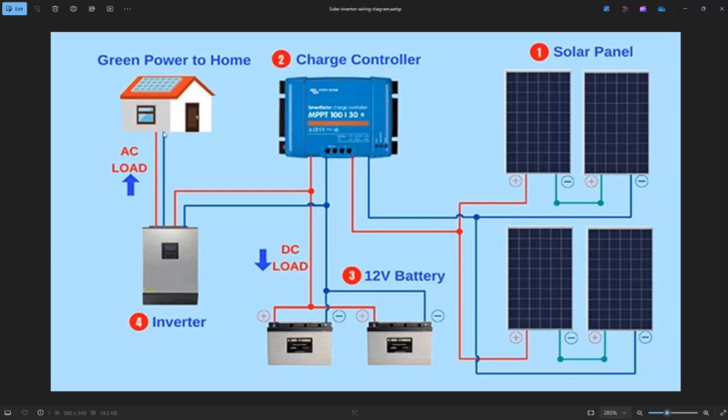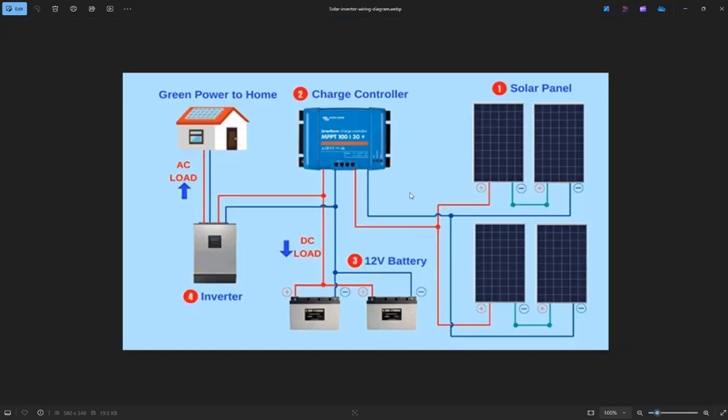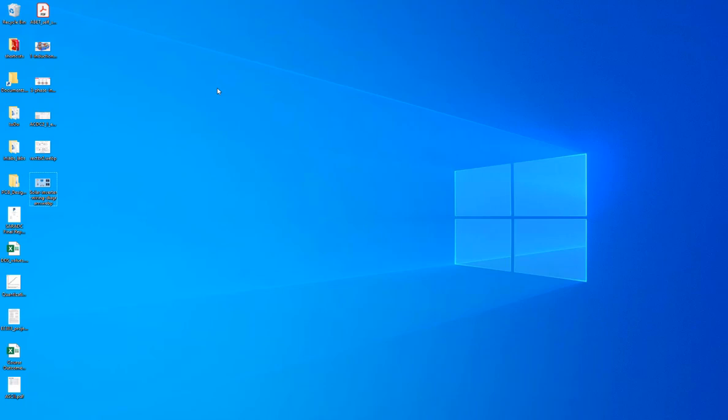You can see people powering up their RV totally from solar panels. You do need an inverter, which is the equipment to convert that DC to 110 volts AC in order to let your old appliances in the house use it. There's also a charge controller, which is able to charge up the batteries. Sometimes RVs have a battery to store the voltage, or stabilize the voltage to 12 volts, because a lot of devices in RVs use 12 volts as input. So those are the two main power strategies most recently in modern society.